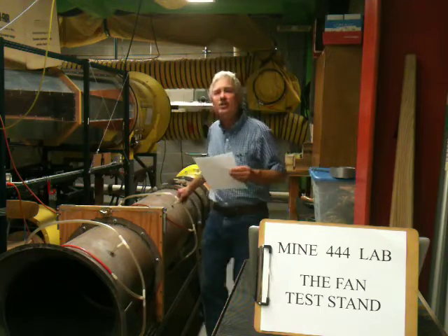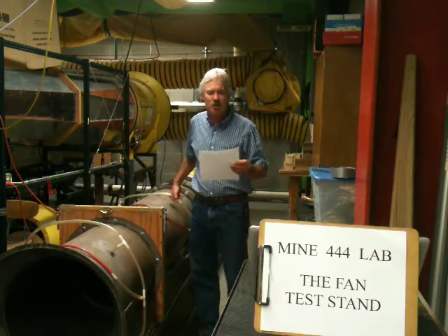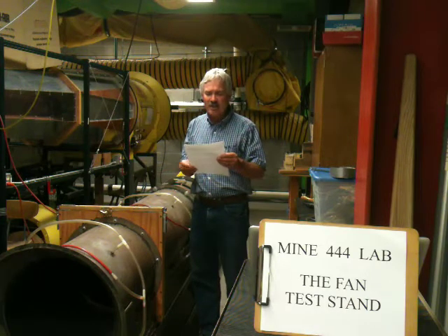Downstream from the restriction box, we have a second set of static pressure taps, and these are used to record the static pressure that's developed or generated by the fan in response to the flow restrictions in the box. So we're going to be recording two static pressures in this lab, but they'll be used for different purposes. Very important to keep that in mind. The pressure at the inlet to the test stand is going to be used to calculate Q from the equation in the British Standard, and the downstream pressure from the restriction box is simply the static pressure P developed by the fan. So it is the P in the P versus Q plot.